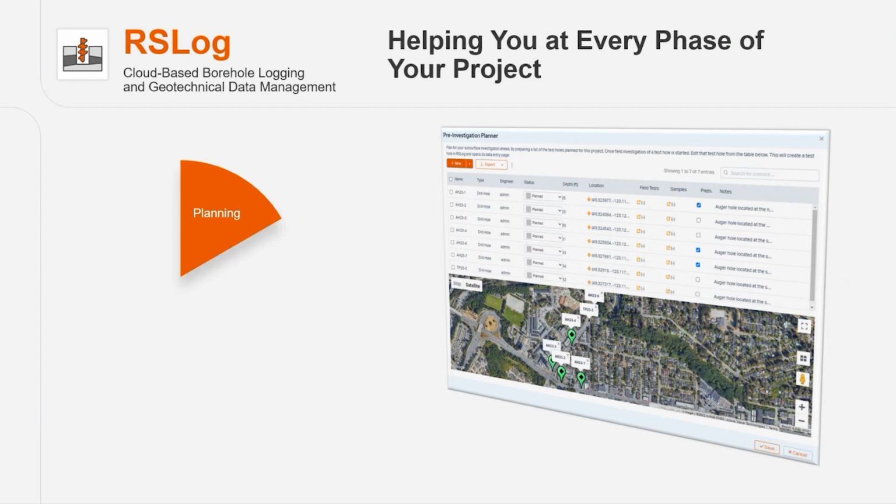These are just some screenshots. So during planning, we have a feature called pre-investigation planner. So the idea with pre-investigation planner is that before going to the site for your next site investigation, you can create a project in RSLog, and you can start creating a list of your proposed boreholes. So these are like the depths of the borehole, the location. You can assign it to different field engineers, what type of sampling or field test you want to do on each borehole, whether you need a piezometer or no.